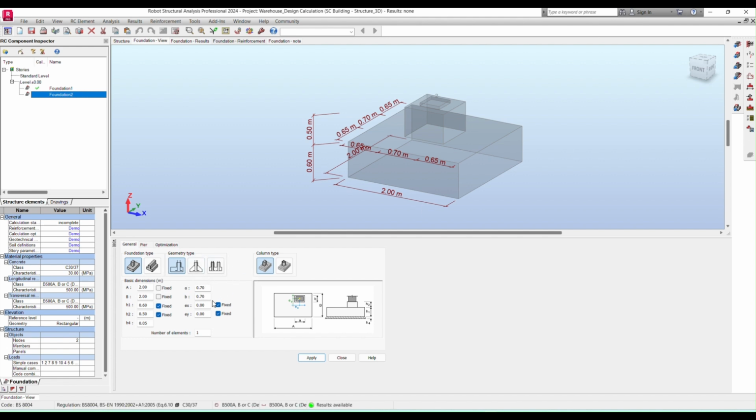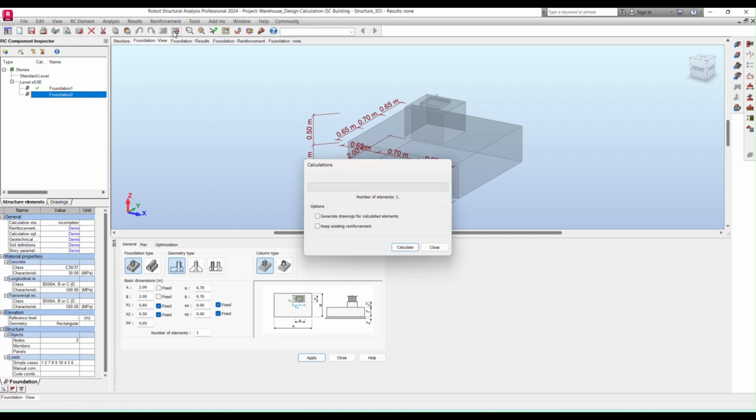So sizes and loads we need to define separately, which we have just seen for foundation 2, and the remaining parameters remain common. Just by selecting this demo itself we can assign all the remaining parameters except the size and the loads. So no need to go to this right-hand icon again and again for the total 14 plus 3 number of foundations of this demo warehouse.